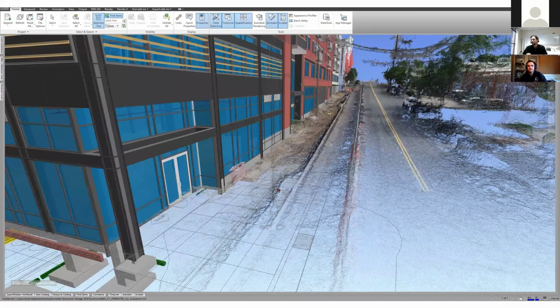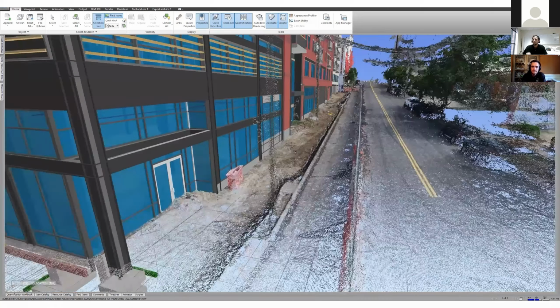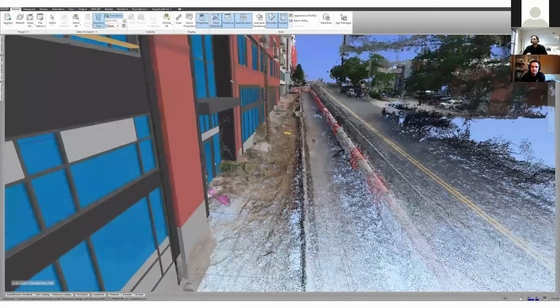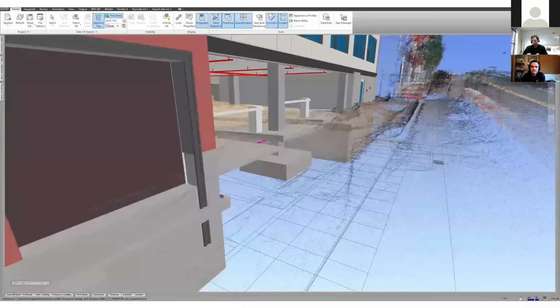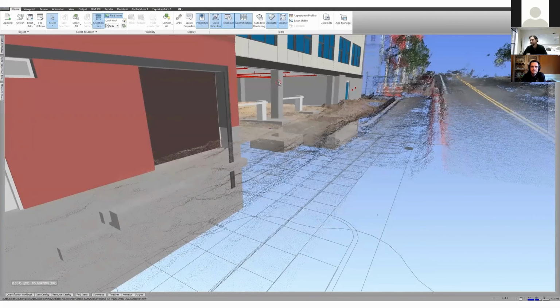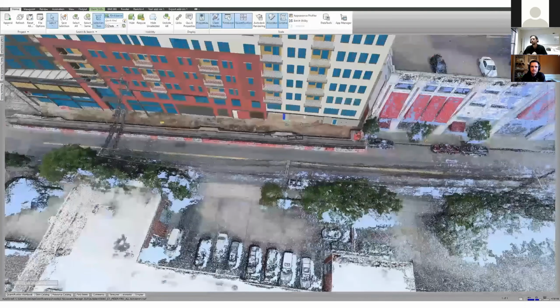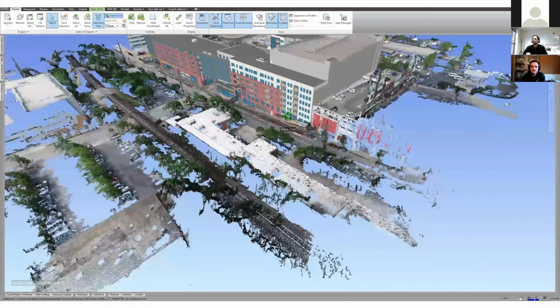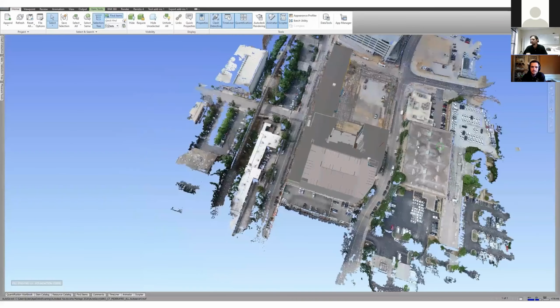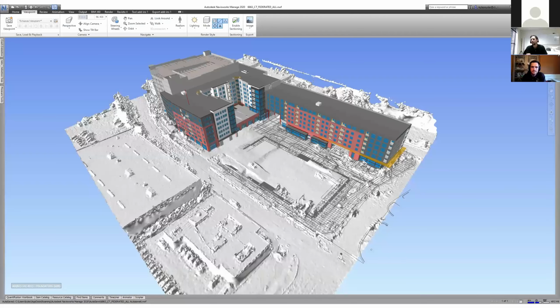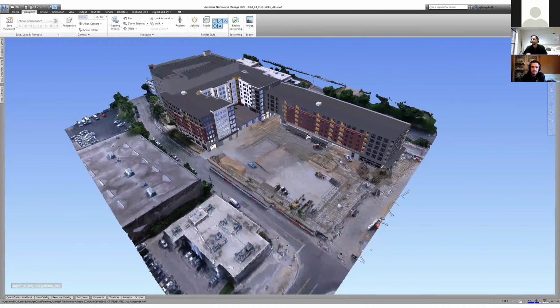And what typically you would do is push all this out and combine it in Navisworks. So here's a view of what that looks like. It works okay for certain things, but as you can see, the point cloud is dependent upon field of view and where you are. So it sometimes disappears or becomes more opaque. And you're also just dealing with the 3D elements here. And then you got these mesh files, which there's a couple other tricks to getting it to show up correctly.